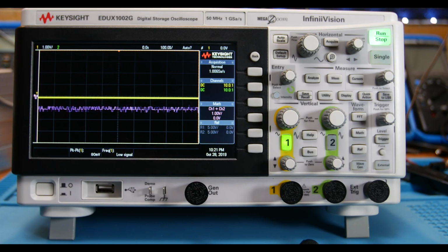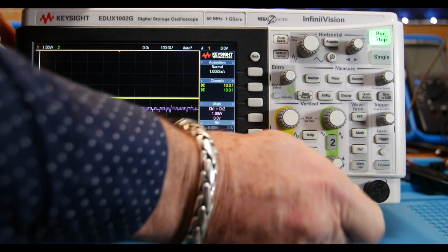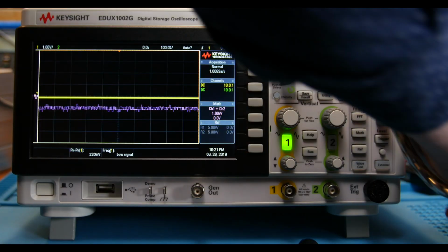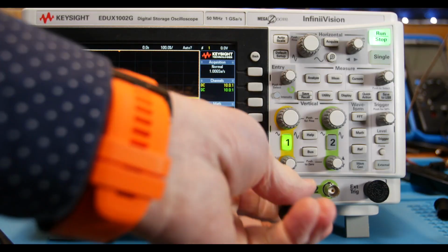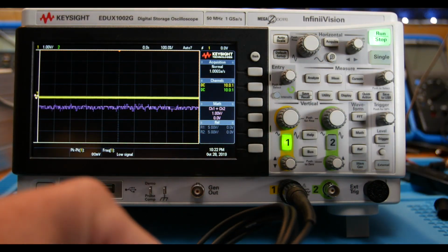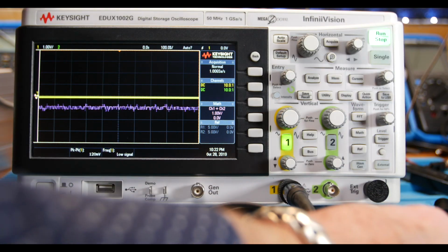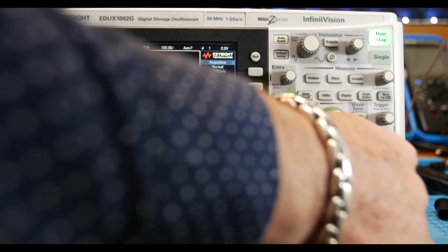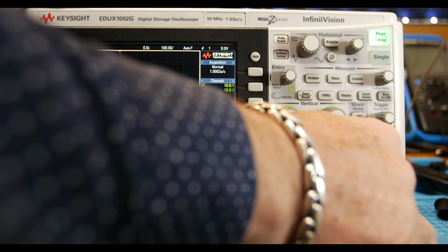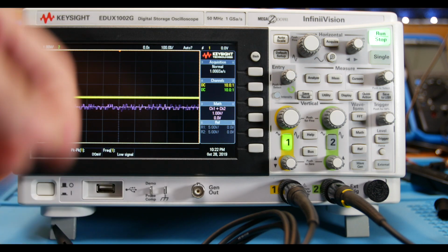Okay, I got another light on that, so hopefully that looks better. Okay, let's get these caps off. We're going to use all these things, I think. External trigger, I won't use. External trigger, by the way, if you're trying to sync up a second scope, maybe you've got so many signals you've got to get another scope, or your project you're running, you want to sync it up with your scope, you can use that trigger for those kinds of things.